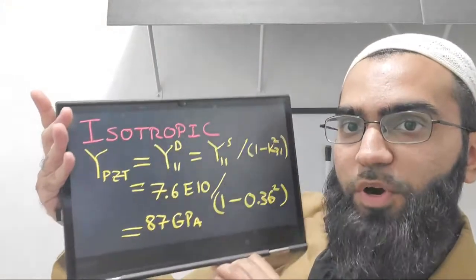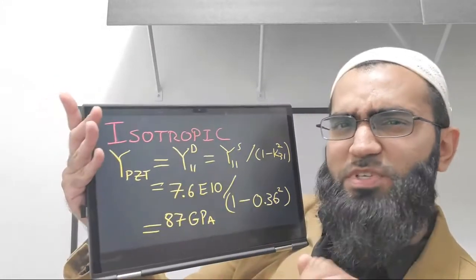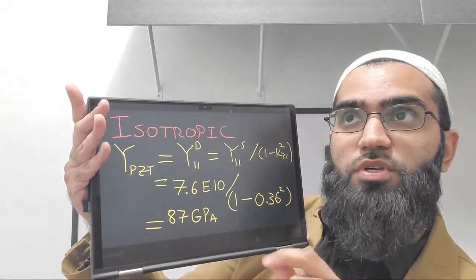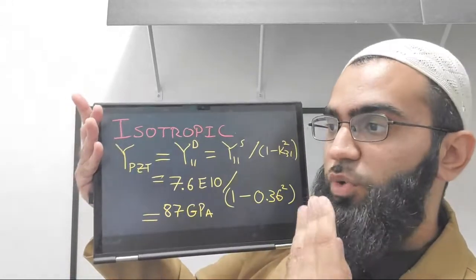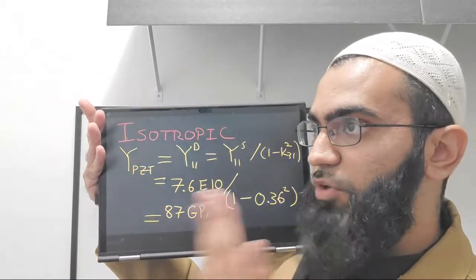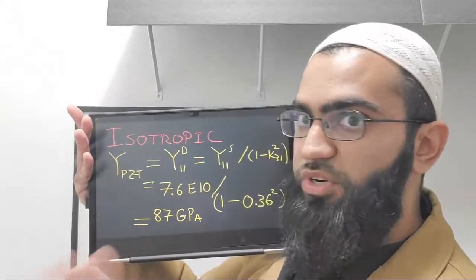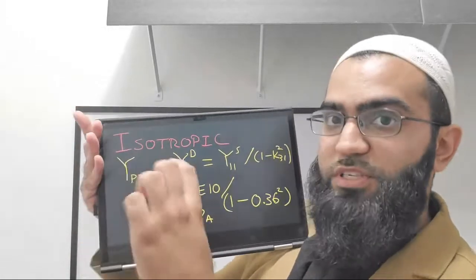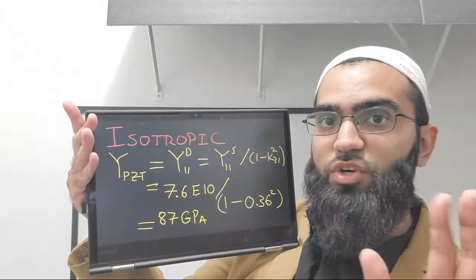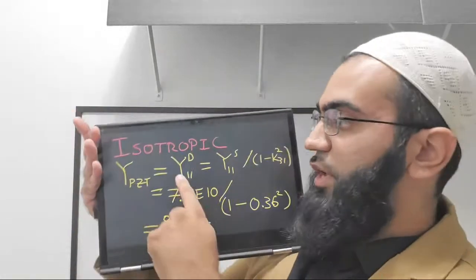This is one of the cool parts I'm going to show you, calculating the relevant material properties, because the specific FEA tool I'm using only uses isotropic material properties. So this is going to be a little bit interesting, to allow us to get a good understanding of what voltages we should expect before perhaps creating your device. So what's the modulus of PZT that you need to put in this case? We're using the piezo as a sensor. In this operation, we're applying a force and we're measuring voltage generated.